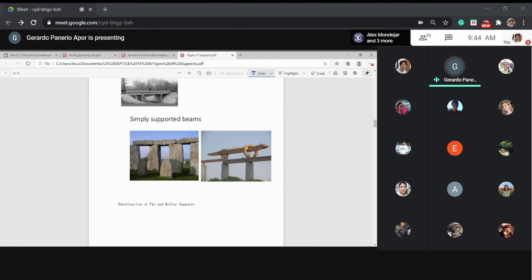Why is it factory manufactured? Because in the factory there's stringent quality control compared to work done on site. And also in the factory, it requires less scaffolding. If you put scaffolding here, money will be wasted. Okay, and it's not very fast. So that's why they precast all the elements and then place them here, no? Then use a girder launcher. Okay, so